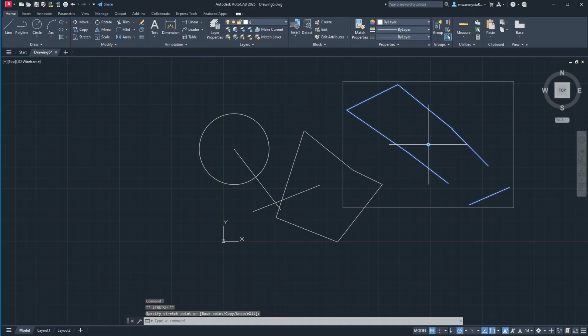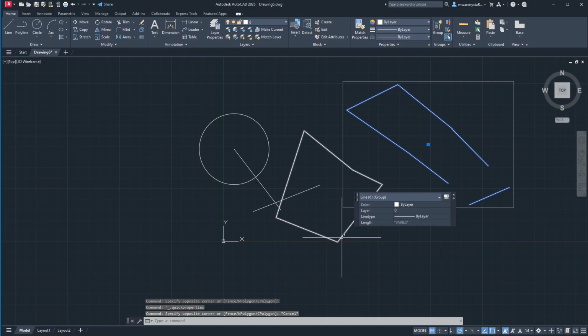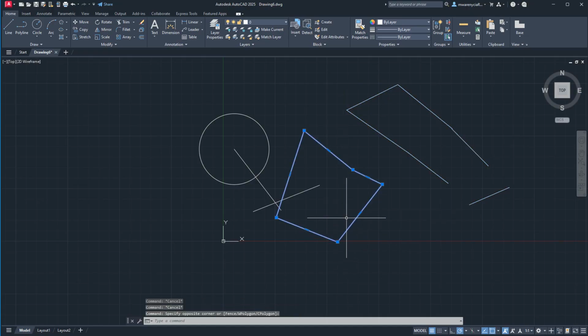That's visually how you tell the difference between a group and this, which is a joined set of lines. Once something is grouped, you would type ungroup to ungroup it, and you can see that this is still joined because you have to unjoin. Oh, right, explode. You have to explode to unjoin that, whereas this was a group and I had to ungroup it. So there's two sets of things, slightly different commands for them.